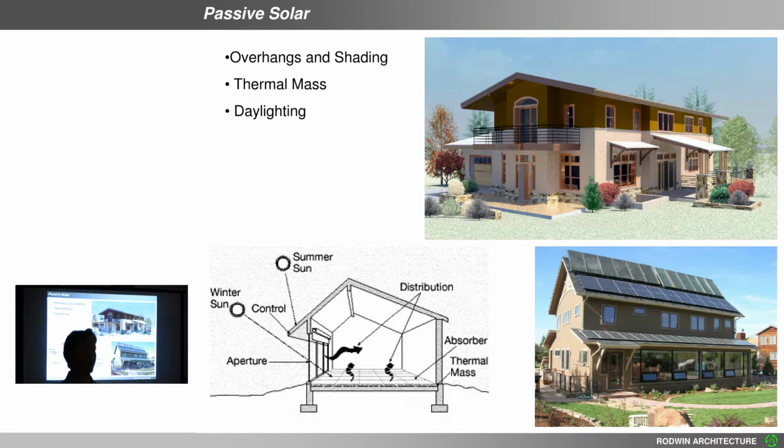It'll heat up the air very quickly. And then in the swing seasons, you might even have to turn on air conditioning. But if you have a thermally massive floor or a radiant tubing in the floor, you can capture a lot of solar radiation and it'll heat up the house very, very slowly. So you won't need to use air conditioning. So again, it's a holistic design process.